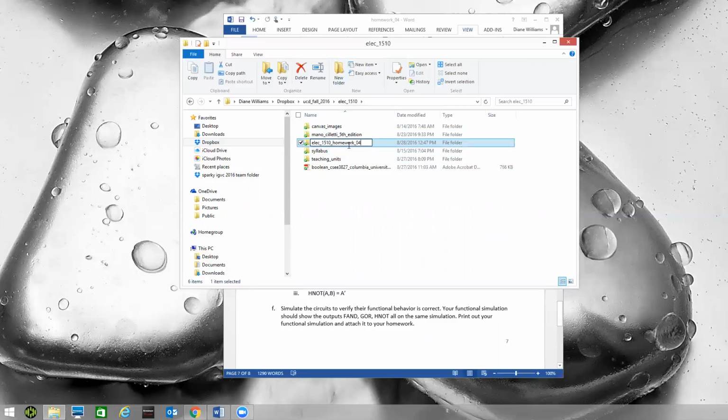This is very important. When you make a file folder, do not leave any spaces in it. Do not put any special characters in it other than this underscore. When you make a file folder name, you're better off to work in lowercase. You want everything to start with a letter of the alphabet. In this case, I started it with an E. So you can use any alphabetic characters in this. You can use an underscore. I did that to separate words to make it easier to read. You can use numbers. Just don't start the file name with a number. So follow a convention similar to this.